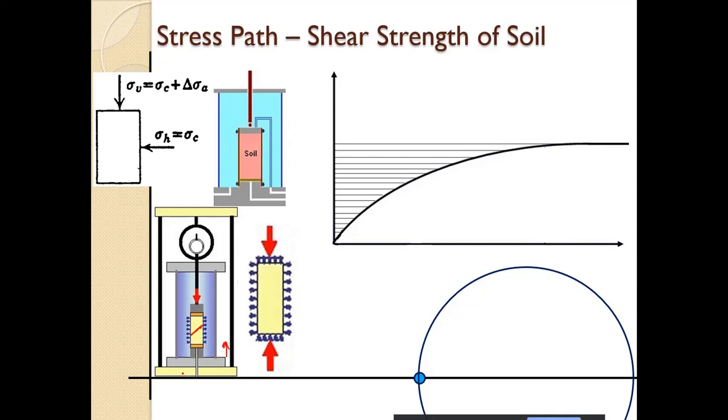Whatever rate it is going up, it may be going up at 1.25 mm per minute, or 0.625 mm per minute. Obviously, the effect of the strain rate we are not considering here. If time permits, we will see that afterwards. We are considering that it is going up at a constant rate.